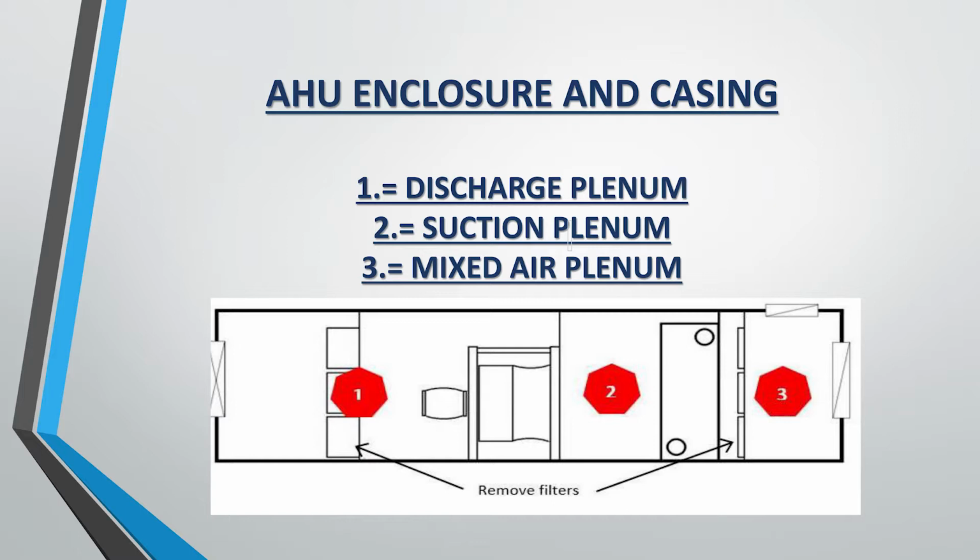Now the AABC standard indicates that you can do positive pressure all the way through if you tape up the exhaust. Well, there's a couple of problems with that. One, if you tape up the exhaust from inside, you can't get out of the unit because you're stuck inside. If you tape it up from the outside and you pressurize this unit, the tape more than likely is going to blow off, or however you affix it. You can't really put something permanent on the outside of someone's unit with these suction doors, because then you'll be scraping it off with a putty knife to make his unit look pretty again. So I prefer to use the doors or the access points that turn out on your suction side rather than the positive.